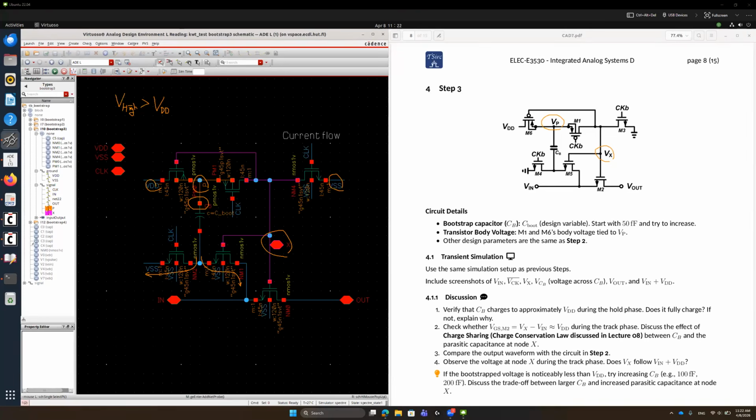High voltage means that, for example, here we have PMOS 1 volt and NMOS 1 volt. That means this transistor can endure as high as 1 volt only. So VDD core, as we normally call it, is 1 volt. For this transistor, VGS, VDS, or VBS, which means body to source voltage, should be less than or equal to 1 volt.